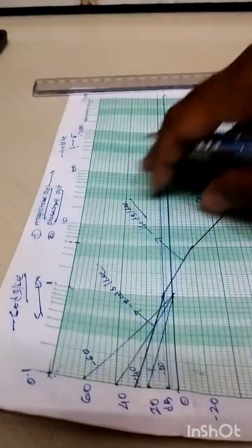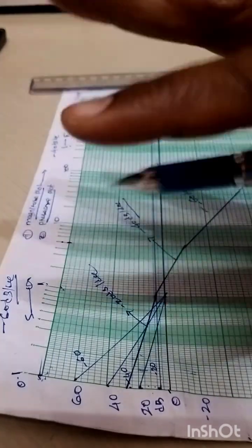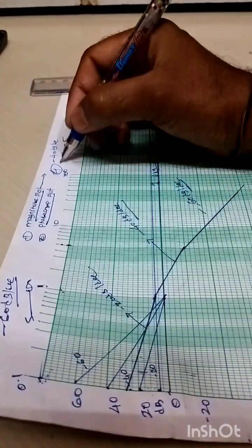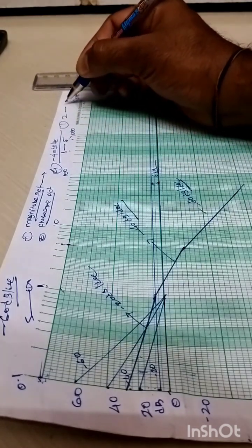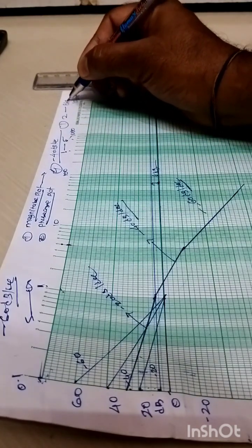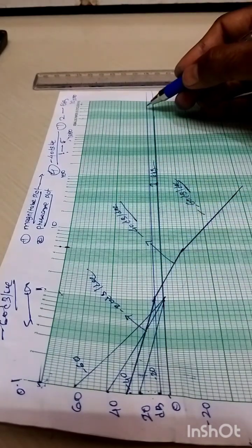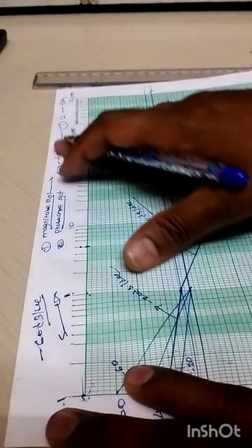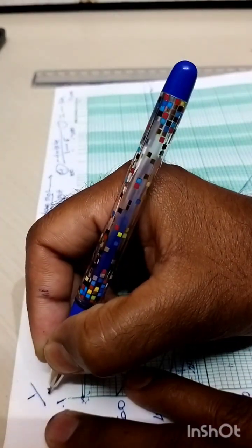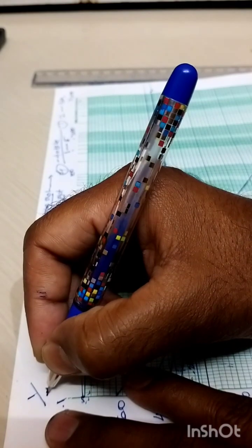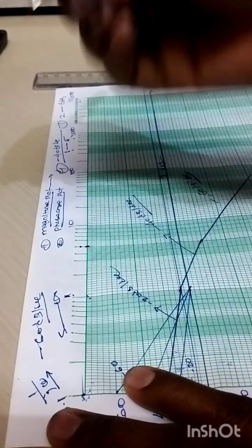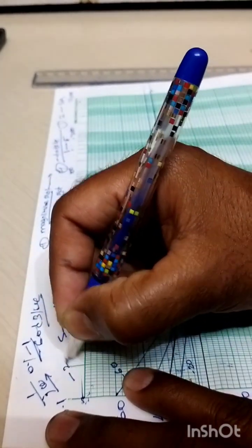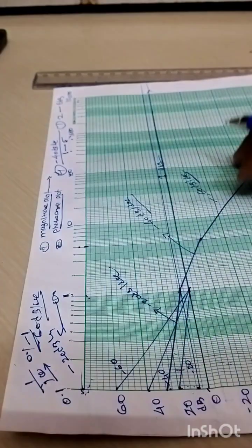So this is how the magnitude plot is to be drawn. So in this magnitude plot there are 4 factors to be considered. Out of that 4, first one is the constant whose magnitude is 6 decibel, right? So this is the 6 decibel line, right? Immediately after that, the second factor which is lying at that origin, 1 over j omega, right, whose starting point is how much, 0.1, and ending point is what, 1, and whose slope is minus 20 dB per decade, right?